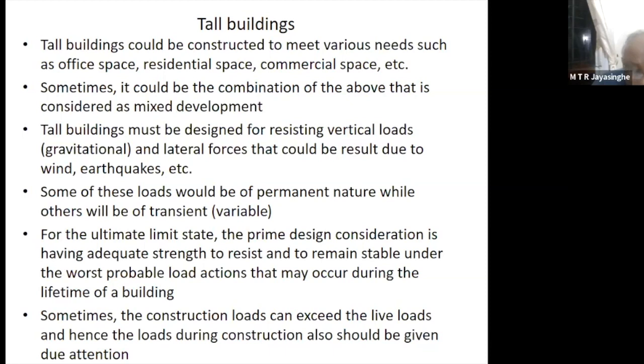Other places, think of using not only 10 millimeter steel, even 8 millimeter steel. And if you break a building which is 56 years old, then you will find they have even used 6 millimeter wires. Today it's not allowed, but you can easily use 8 millimeters. But when you use 8 millimeters, you have to have some timber planks on the steel mat, because if you walk on the steel mat, it can deform. So you need to have sufficient timber planks on the slab for walking.